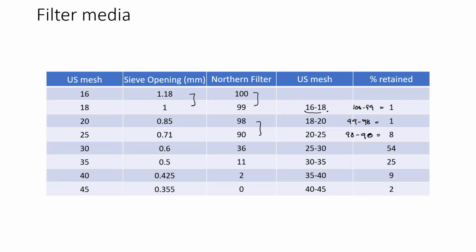Notice here, we're looking at that retained between two adjacent sieves. And if you're not used to this, as the mesh size increases, notice your sieve opening decreases, and it's purely convention.